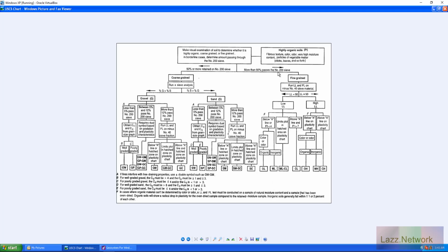So as we get into our fine-grained material, which is silts and clays, good lord. I'm losing my mind here. With our silts and clays, this is kind of following the exact same mantra, where our silts are usually going to have a low liquid limit, and then our clays are going to have a high liquid limit, because clays can hold a lot of moisture.